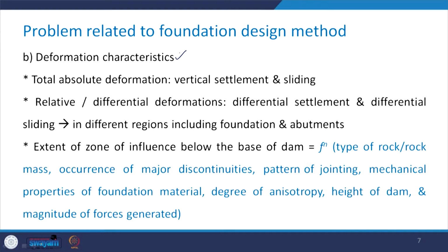of these dams. The second aspect includes the deformation characteristics. As far as the total absolute deformation is concerned, there can be vertical settlement as well as sliding. For relative and differential deformations, again in this case you can have differential settlement and differential sliding.